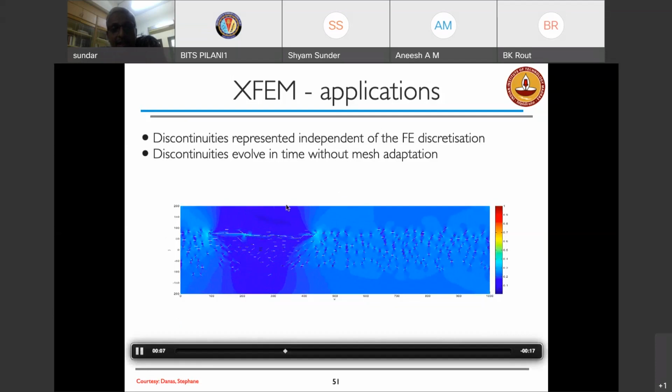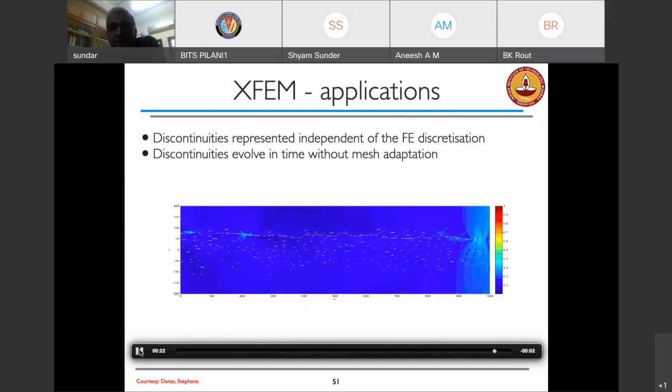So you saw that the crack actually stopped growing after a while, and then the right part of the crack started growing. It started to merge with other cracks as it propagates. So that is a merging again. It changes path. Then momentarily this part of it stops and this side grows. Again, all this comes from the local energy criteria that is available for the system to dissipate. So a very complex crack pattern can be captured with much less computational effort.